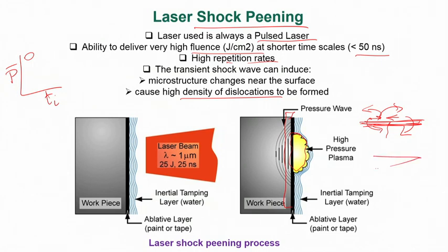So if you have, for example, a component, a sharp teeth of a gear component, or sharp edges of a cutting device, or in a semiconductor you want a small region to be heated and leaving rest of the regions unaffected. So very precisely you can heat treat only this portion, the dimension of which could be few micrometers, and remaining 90%, 99% of the surface can be left unaffected.